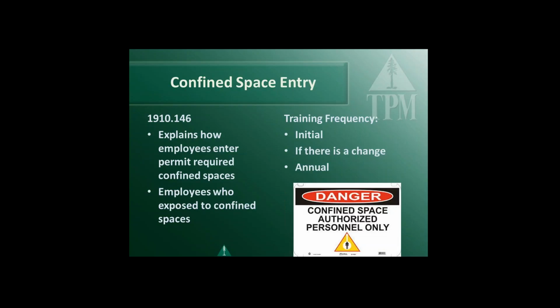So what we want to look at is who is involved in the confined space. If you're handing someone tools, you are considered exposed to the confined space and you need to be trained. Well, I don't go in there. It doesn't matter. The way the law reads, if you're exposed to it, handing tools, even around it. Because of human nature, because we're good people and we always want to help. If someone gets hurt and someone falls or someone's in there saying, oh, I need help, what are you going to do? You're going to rush in there and save somebody.